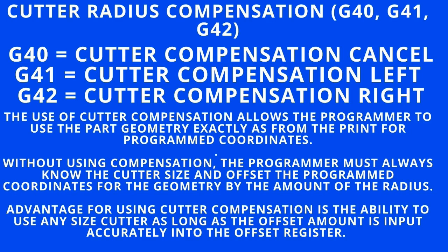Today we will study cutter radius compensation: G40, G41 and G42. G40 means cutter compensation cancel, G41 means cutter compensation left, and G42 means cutter compensation right.